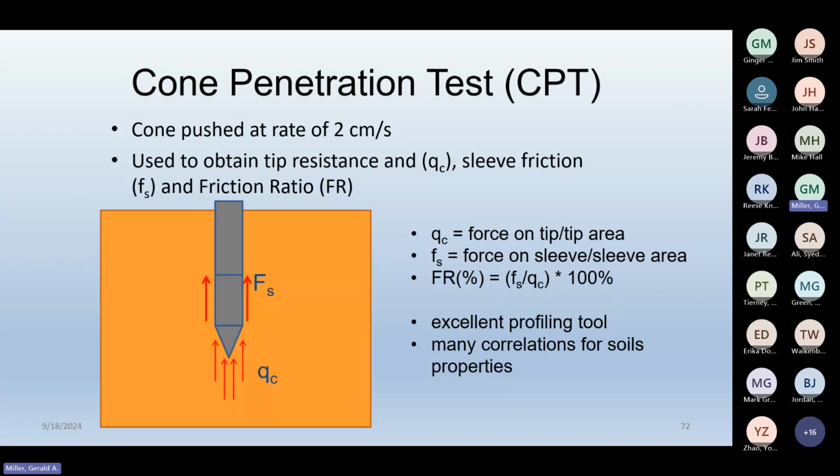Well, if there's an air bubble, that air bubble is compressible, so it has to adjust its size in response to a change in pressure, which means that by the time it adjusts its size, you're already down here. So the pressure you're measuring is not the pressure that was up here when you recorded it. So it's called hydrodynamic time lag, where the variable compressibility of that fluid affects the measurements and how they correlate with depth.